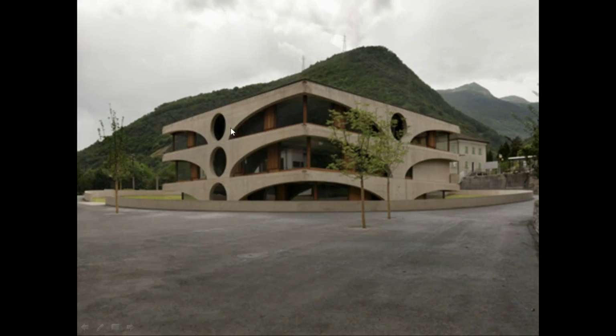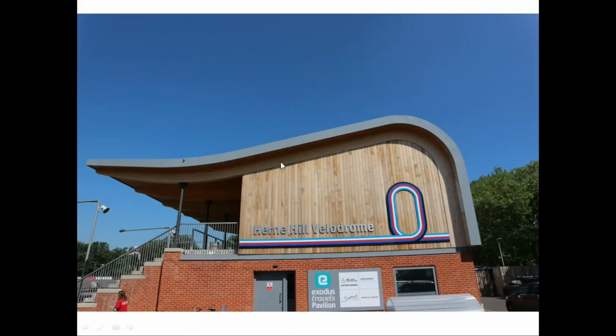But let's just look at one other little, okay, it's lovely to have this opening here. This is actually a school, by the way. It's designed as a school building. It's nice to have the porthole openings, but of course they're also taking mass away from the structure where we don't need it. So they're making the structure lighter. We don't need that to be solid concrete. You're triangulating already here. If you can see, there's a top rail. If you just reduced it to a series of triangles, you can see it's a little bit like the Forth Rail Bridge. So you're taking away mass, which is always a good thing. Take away the dead load. The less the dead load of the building, the better it is.